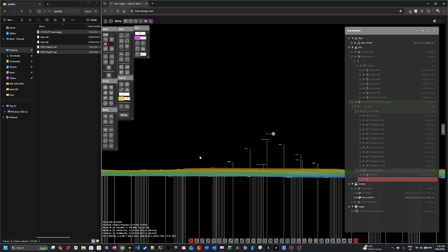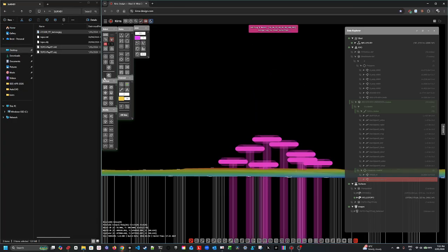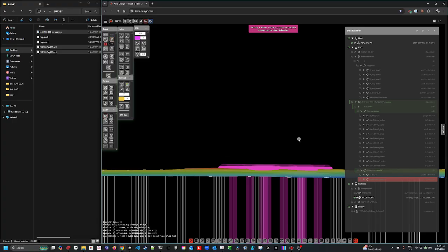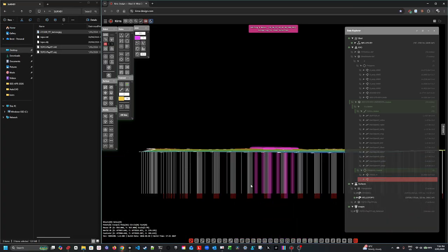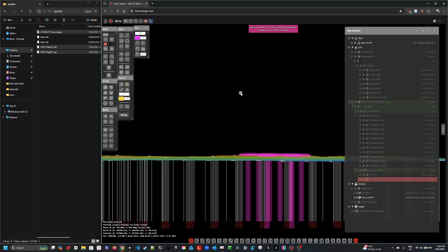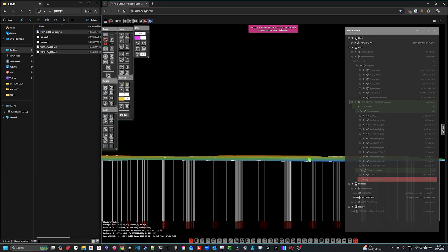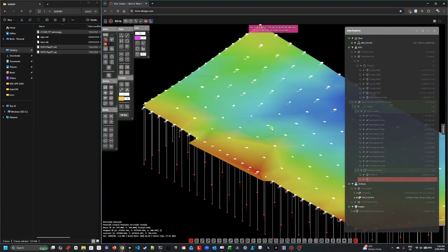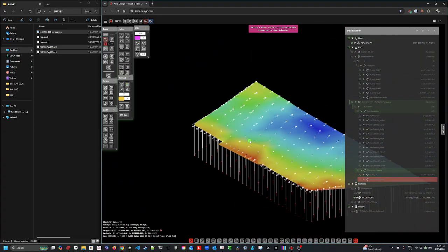So let's just grab the holes that we need through there. Got our holes and we're going to stick them to the surface. Okay. Right, now it didn't ask me for the surface because it's the only surface available, so it stuck it to them. Okay, and the toes are still in the same spot. So we didn't get an option to ask because it's the only one visible. So if you had another surface visible, you get asked. Okay, so now we've got our blast done.